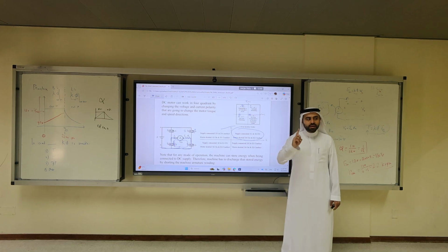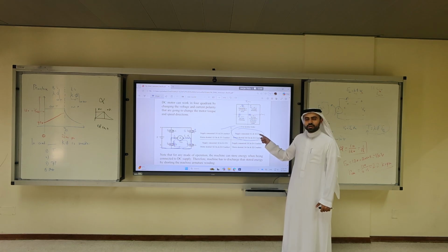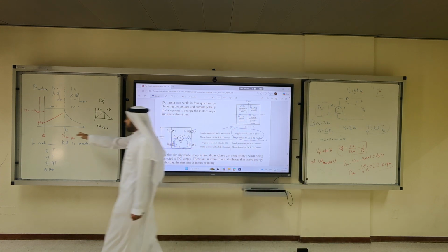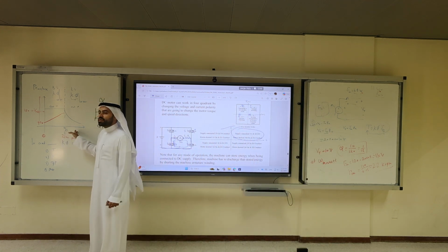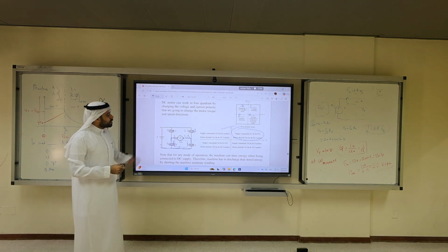But keep in mind, never ever keep S1 and S4 on, because if you keep it on, what will happen? You will reach rated speed, the maximum in your omega base. Remember, we're not playing with the fields. Here we're doing constant torque still. Okay?